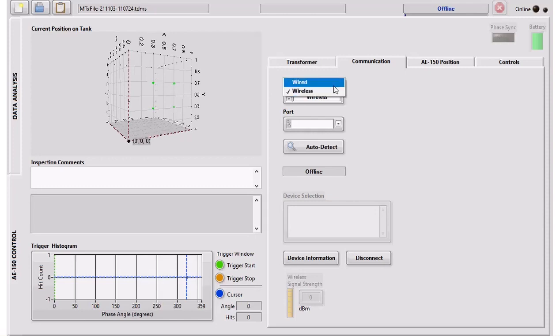So let's say if you're wired or wireless, any of them, you will need to select a COM port attached to it. So either you're wired, so the unit will be seen as a communication port, and same thing if it's wireless. The communication link is seen as a communication port. So you refresh, select it, and connect on it.